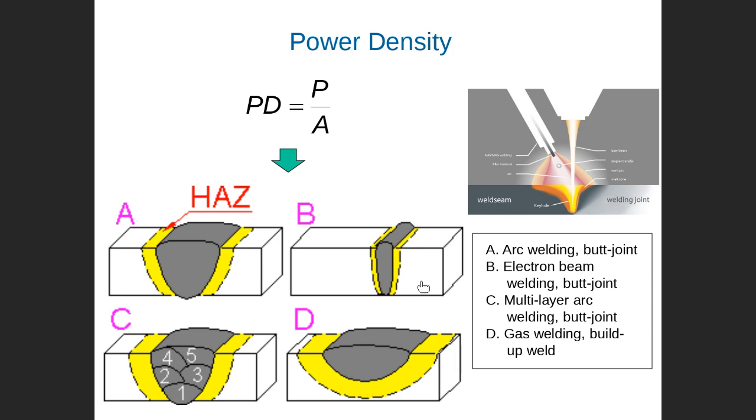That's why if you would like to make a deep hole, you need to have high power density, not heat, not temperature. For example, if I say that to make a deep hole you have to have a higher temperature. No, not high temperature, but high what? Heat density, power density. Right? You understand me? So this is what we would like to say. So focus, it is narrow but deep because the power density is very high.